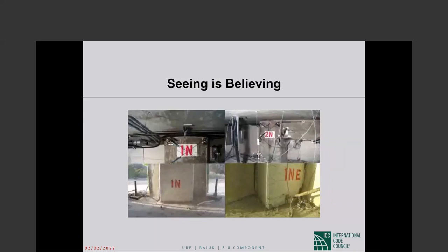The only time we have to include a part of the live load in seismic mass is if it is a storage facility. If your question is about what we call seismic weight, that is a term in ASCE 7 and BNBC, seismic weight or seismic mass.